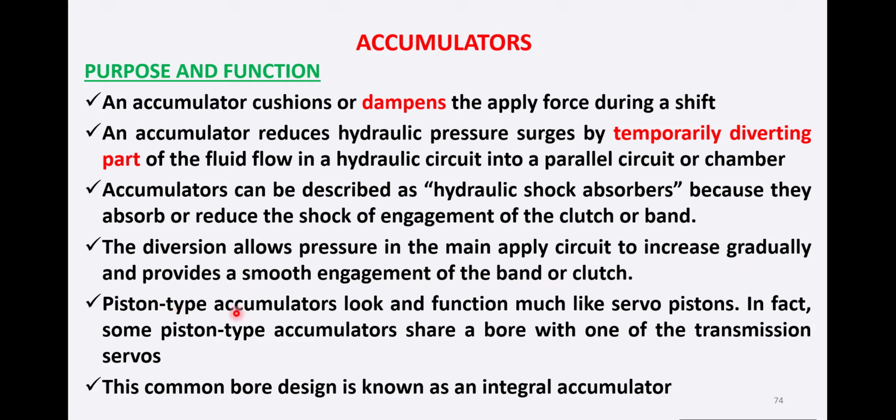Piston type accumulators look and function much like servo pistons. In fact, some piston type accumulators share a bore with one of the transmission servos. This common bore design is known as an integral accumulator.